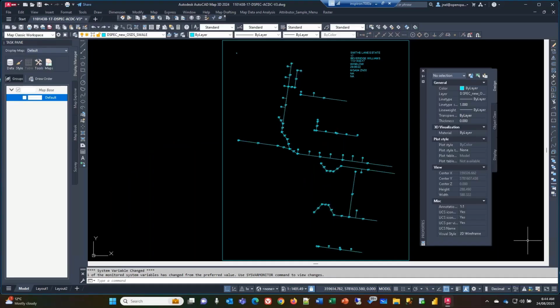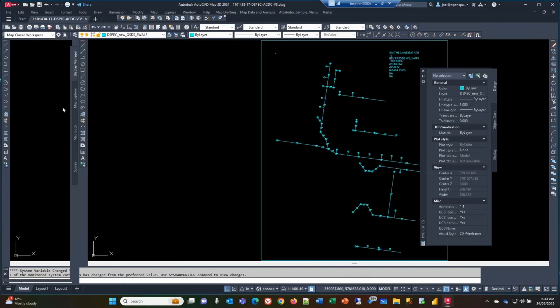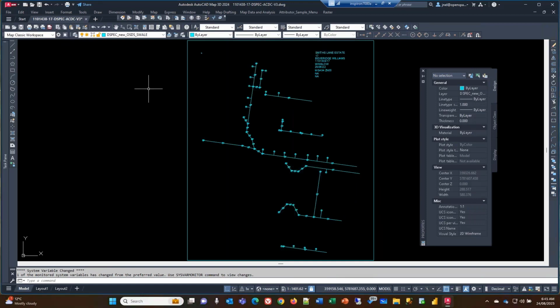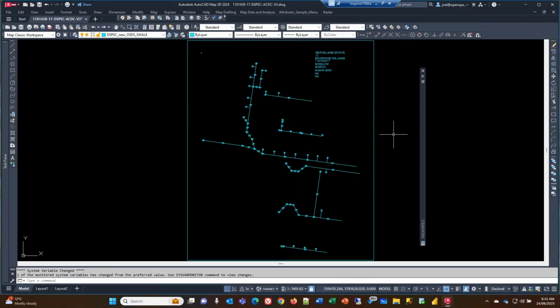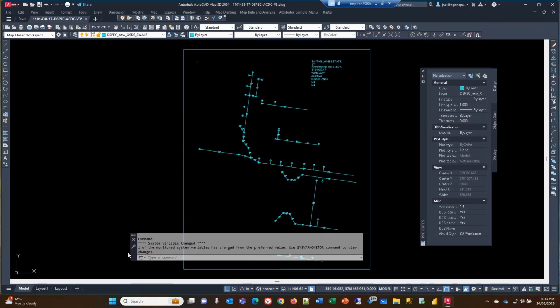So just basically, in terms of our user interface, I'm running AutoCAD Map here. So here we've got the toolbars. This is a task pane. Anything where you work with any of these, you can easily dock them just by grabbing that. One of the other things you'll see here is this little funny icon. What that does is collapse any of the panes, which reduces the amount of space, and then if you hover over it, that panel will pop out. I'm going to leave mine popped out in this case. The task pane I'm going to turn off. So here's then our command window.